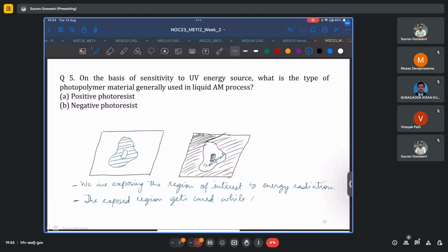We have also looked at the case which is similar to deposition of a weld bead, where we find that at the beginning the bead bulges, in the middle it is quite uniform, and at the end it bulges again. Of course, rather than a bulge, it can also be a dip. That is, you have under deposition at the beginning and at the end. Thus, both the start of print and the stop of print are regimes in which the process does become unstable.